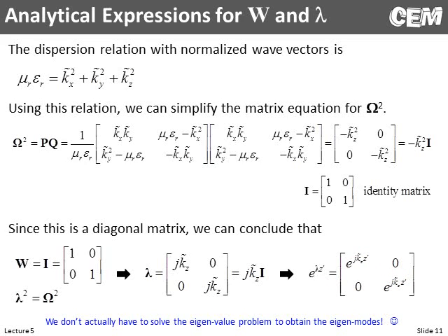I recommend extracting the diagonal from the matrix, do your math in, take the square roots, take the exponentials, and then inserting that diagonal back into the square matrix. And the reason I say that is I've had troubles with the matrix exponential function in MATLAB before. In this case, I don't think it's going to give you any troubles because it's a nice, well-behaved diagonal matrix. But later on, these will no longer be such easy matrices, and I have run into troubles.